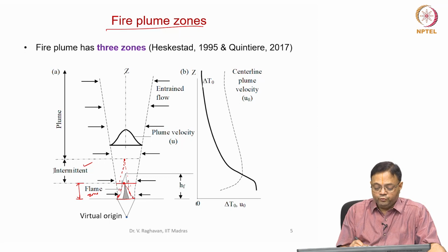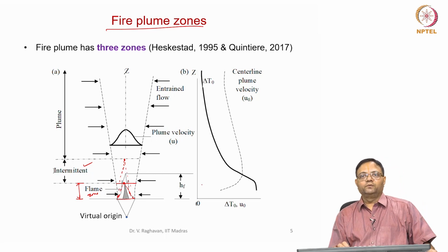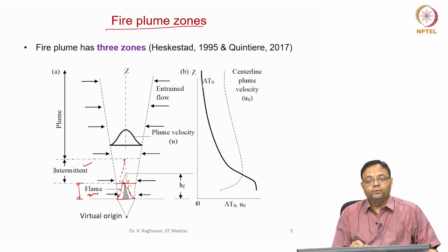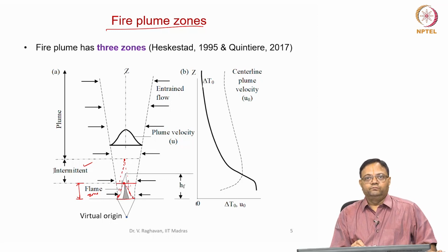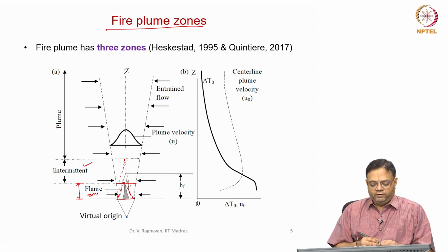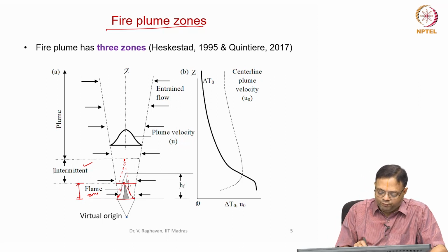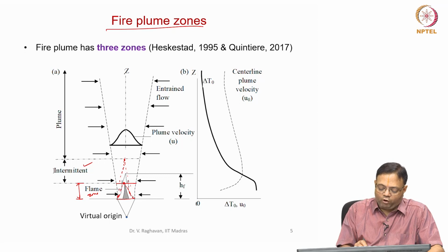So, in the intermittent zone, we will not be able to see the flame at every location always, because the flame oscillates up and down, while within the flame zone the flame is always seen. So, we can use any optical method or temperature probing, etc., to understand the height where the flame is always present. After that, the flame will be oscillating basically.